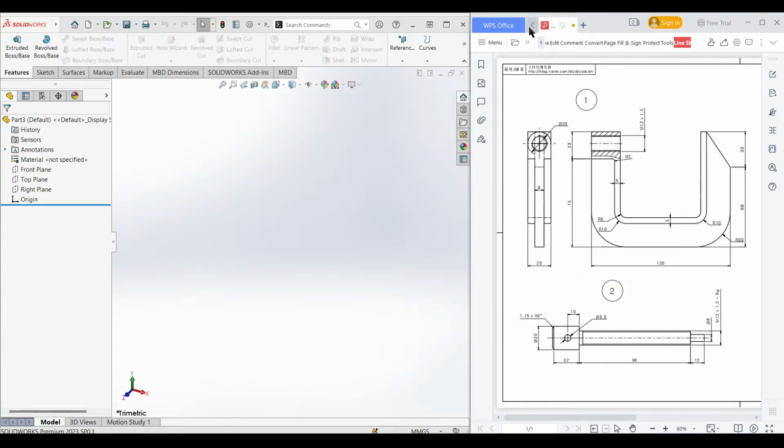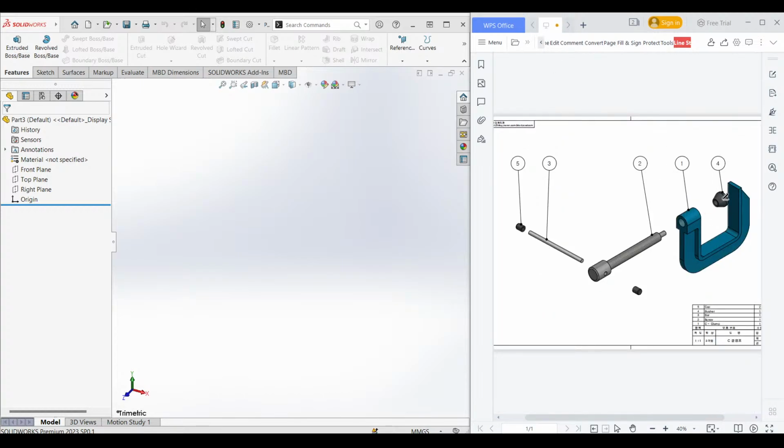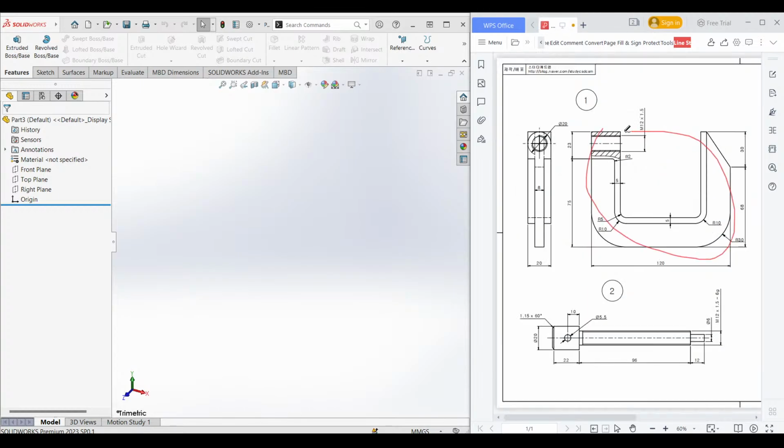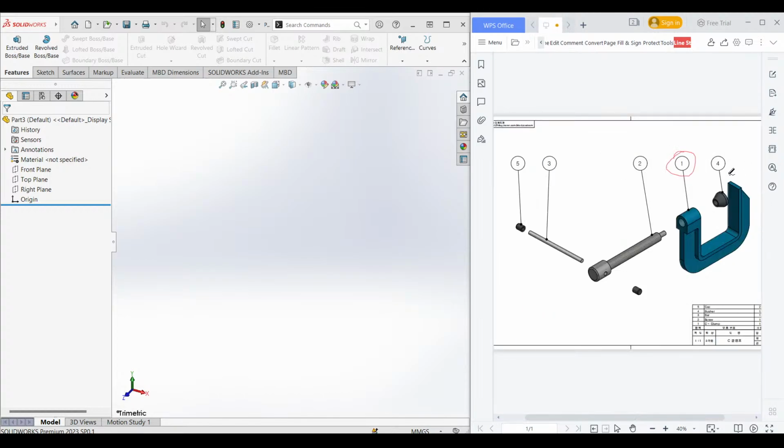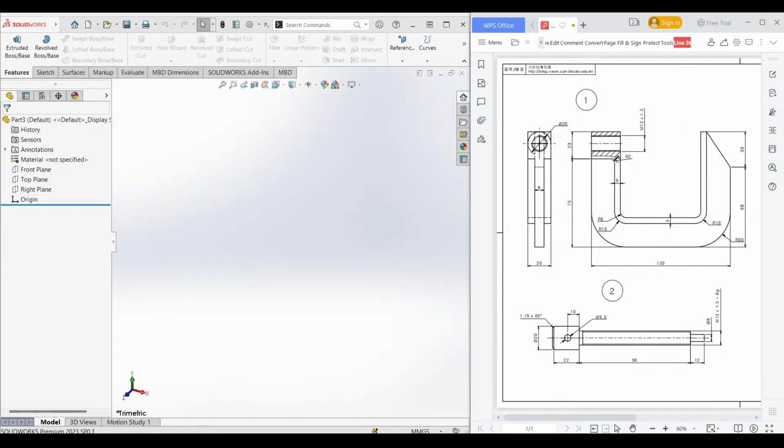If we look back to our main assembly sketch, the number one sketch is this one. This is our right view, and this is our front view according to this sketch. Okay, let's go back to our sketch. In this sketch, I will start drawing from the right side or right plane. In the right plane, I'll first of all select the line tool and draw a vertical line of 75 unit.